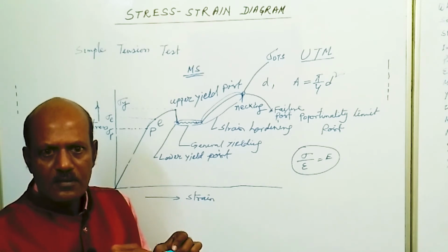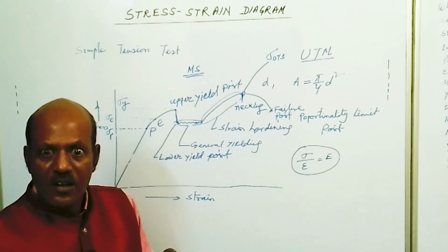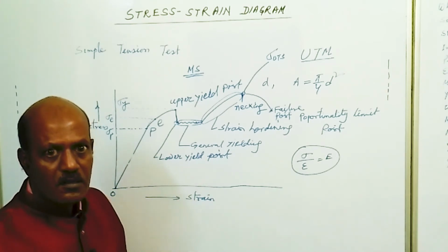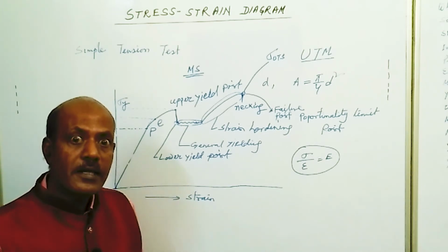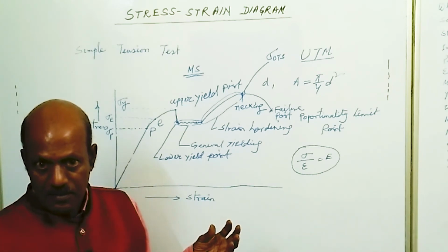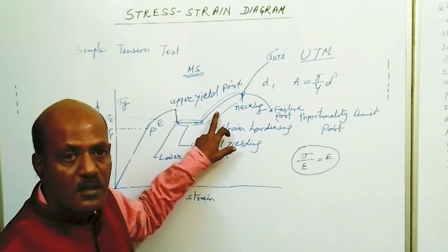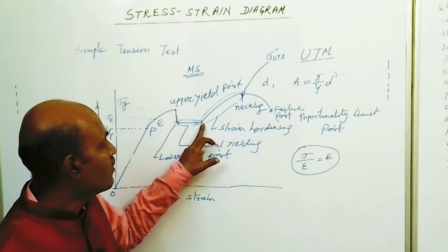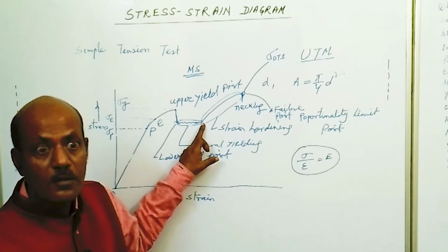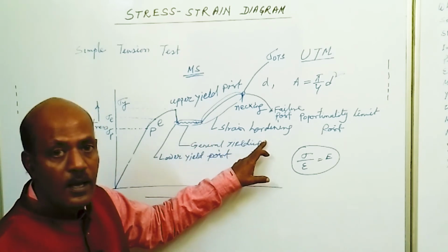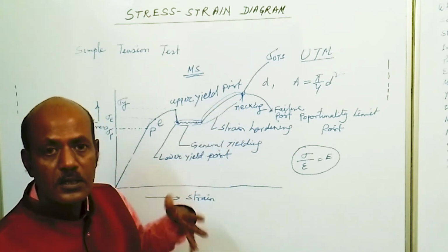Then you apply the load over this wire. After some times, 3, 4 or 5 times, you will find that more energy is required for bending that wire. That means whenever we apply energy over a body, some of the energy is absorbed by the body and is not released. Thereby the body becomes stronger. So this is the phenomenon taking place after the general yielding is over. The body becomes hard because of strain hardening, thereby the load required for further deformation in this zone increases.